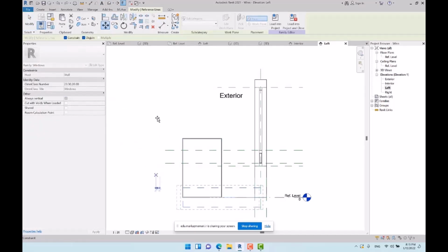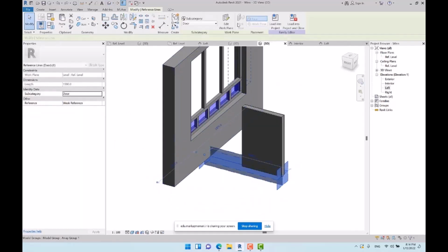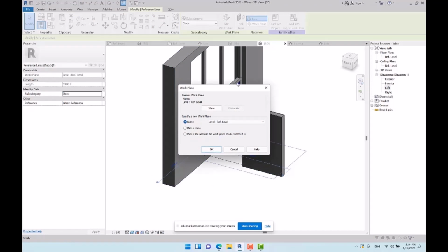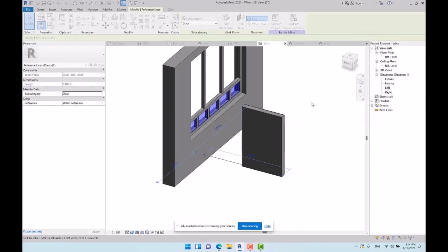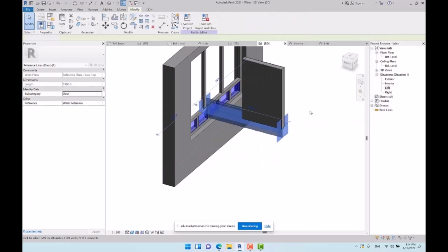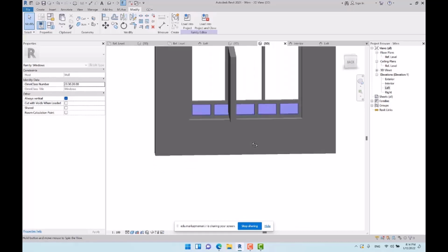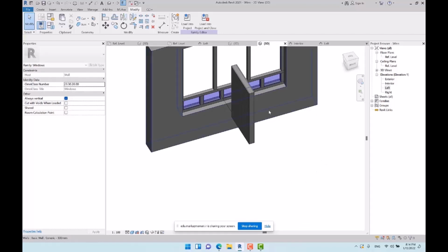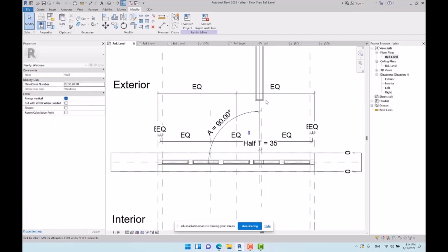Even if you select the reference line, to move it by using move tool, as you can see, it is not available. So the only way is to select the reference line and then edit the work plane and then set the specified name for the reference plane, which was base top. Okay, check this out. This was an important point that you should know, because some details are so effective in carrying out a process, and these points are applicable in all of the projects.